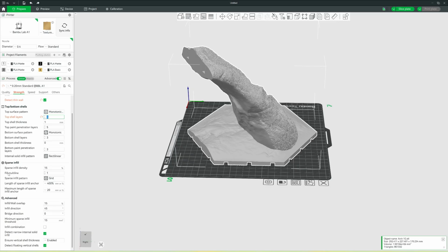And then here's where we're going to start making some adjustments: the sparse infill settings. I like to set this for 10%. And go down to lightning fill. So what this is going to do is your global settings, it's going to set everything to these parameters.